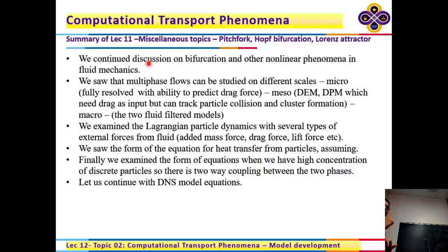Now, to trigger it to go to the cellular mode, as you increase the rotational speed beyond the critical value that I've given in the table, pick any one of them and just go across that boundary. What you will find is that the default 100 iterations may not be enough because there are significant changes in the flow pattern. It has to develop from almost 0 velocities to very strong finite velocities beyond the critical point. So you may need 1,000, 2,000, 5,000 iterations. One thing you may want to do is increase the number of iterations and let it run for a longer period of time.